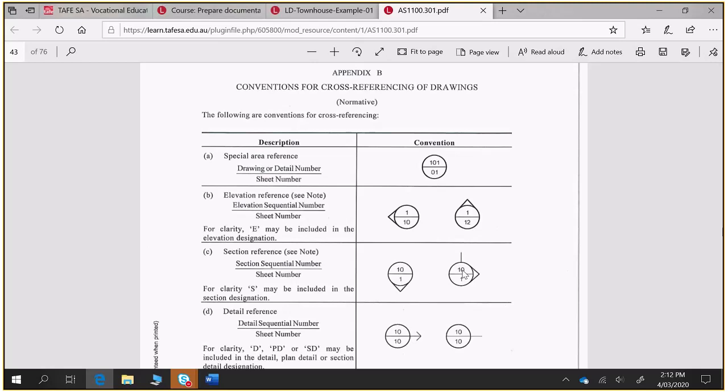What I've typically done is whenever I'm doing sections, I call sections A, B, or C. So I use letters for sections. I use SD1 or PD1 for section detail, right? So SD and then a number for the section, or PD for plan detail. Sometimes you'll have CD as well for construction detail. Your details are numerical, your sections are letters, and then your elevations, I typically do them as 1, 2, 3, 4. And we mentioned that before.